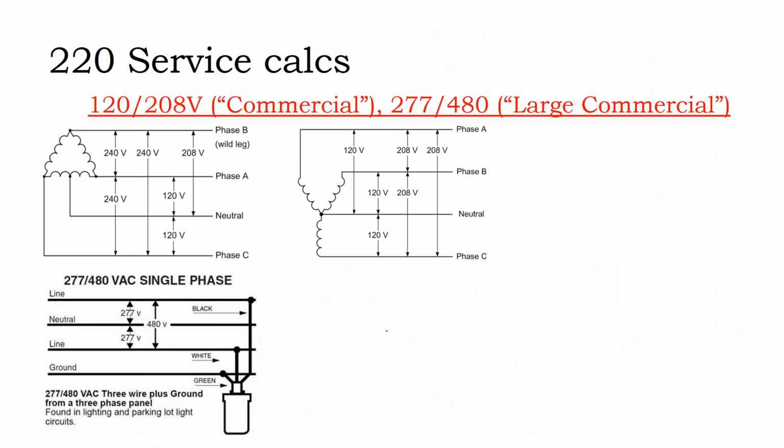Well, maybe or maybe not. If one circuit and another circuit both have load on it at all times, maybe it only needs to be sized to carry the difference between the two. And so you get into the concept of, under some circumstances, you can have an undersized neutral, and under other circumstances you can't. You know, on a solar array, there's really no reason to have a